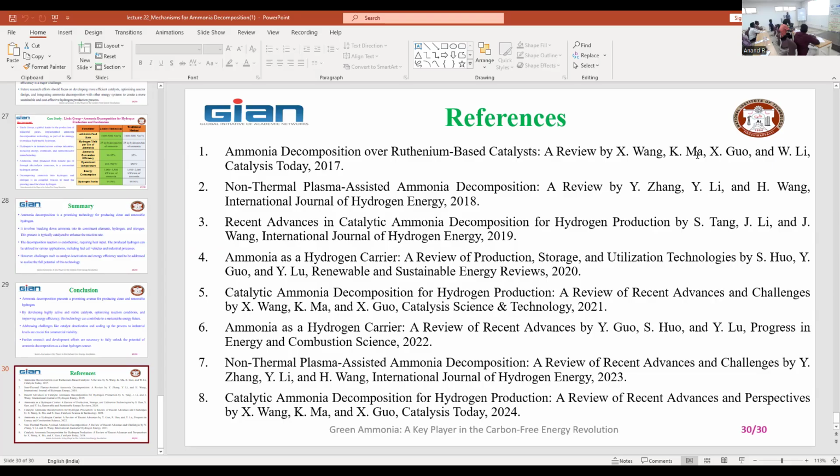So we use copper in many places to avoid leakage, right? Wherever the copper components are exposed, similarly even for the fuel injector and fuel pump, there are some elements associated with copper. Copper is prone to oxidation, and biodiesel contains oxygen. Here, I don't think there is a problem of oxidation, because ammonia contains only nitrogen and hydrogen, but it is corrosive in nature. The property itself is corrosive.